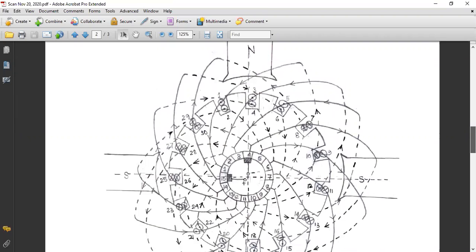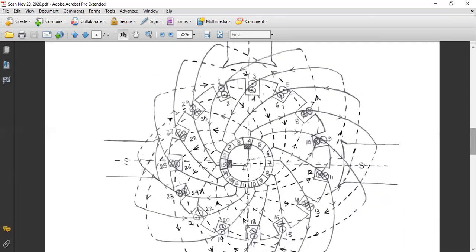So first you have to place the marking dot and cross on the conductors, and these are all double layer winding, so there are two layers, two conductors in each slot. Now under the north pole dot, and under the south pole cross. So this is how he has made this. Then he has shown all the coils as per the winding table already made. He has drawn the coils, like one coil is starting from commutator segment 1 and passing through the coil side number 1, and returning back from this 10.